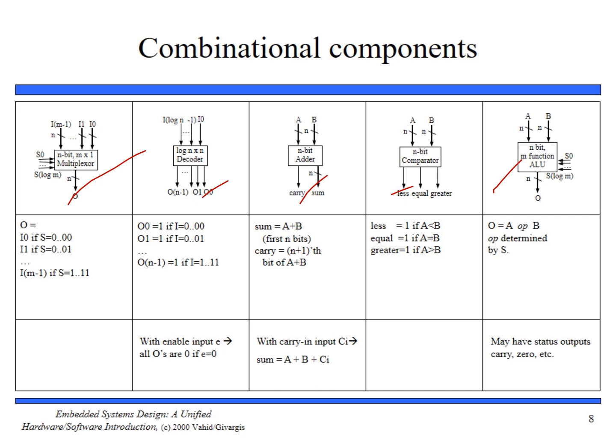So combinational components are often called register transfer or RT level components. So these are RT level components. Now here, number 1: a multiplexer, sometimes called a selector. Why do we call it a selector? Because we select the data inputs, allowing only one of its data inputs, I0, I1, up to IM-1, to pass through to the output. So this is output O.